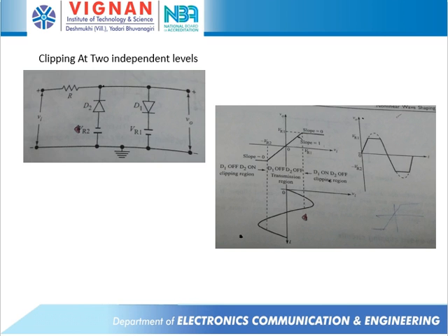And in the third case, when you are providing an input potential Vi greater than our Vr1, in this case D2 is reverse biased because the anode potential is less than the cathode potential, and D1 is under forward bias because the input is more than our reference Vr1 potential. Then D1 acts as a short circuit. So when D1 is acting as a short circuit, the Vr1 reference that we have itself represents the output, so you can say V0 equals Vr1.